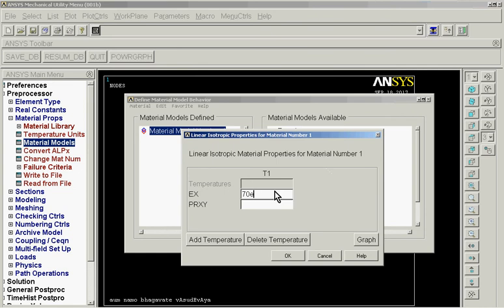it to 70E3, reminding you that ANSYS does not have any system of units, and I can basically use any consistent set of units that I need. Just make sure that you interpret the results in the right units that you have set in the beginning. So I'm going to use the values of Newton per millimeter squared or megapascals. The Young's modulus is 70 megapascals. I'm very sorry, 70 gigapascals, and hence I am writing 70E3.